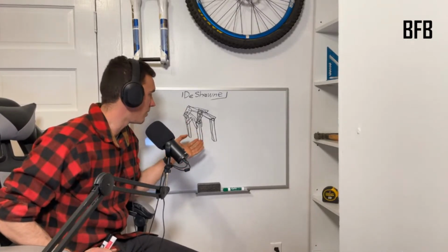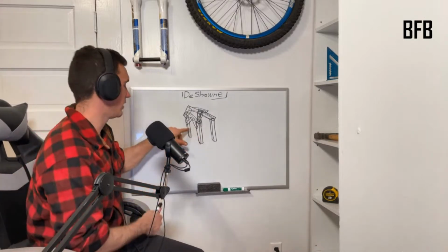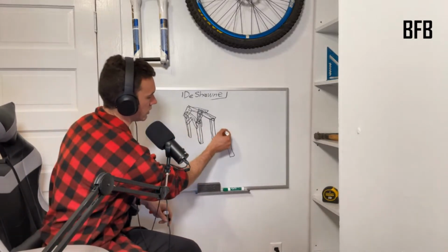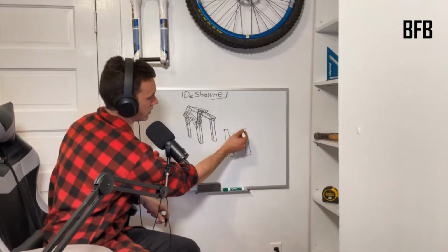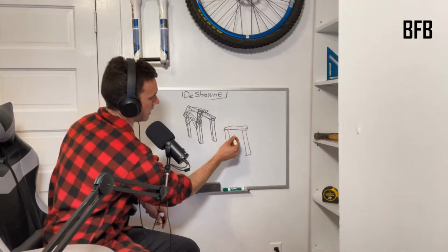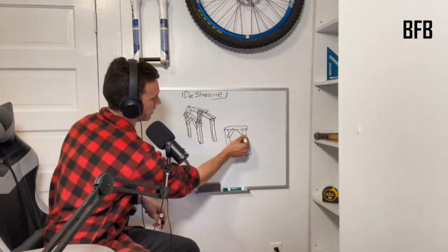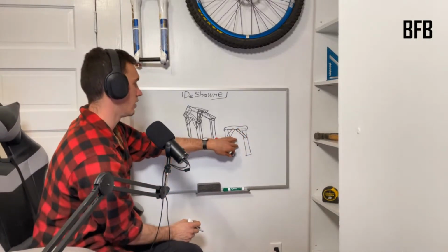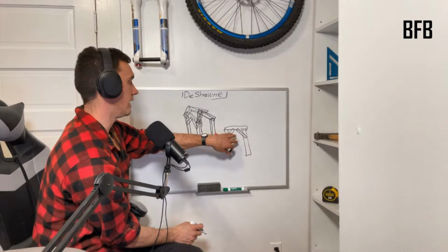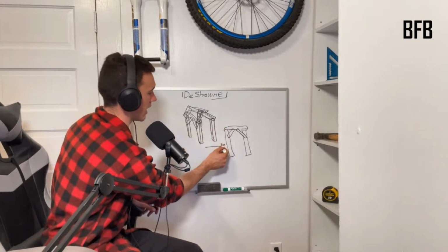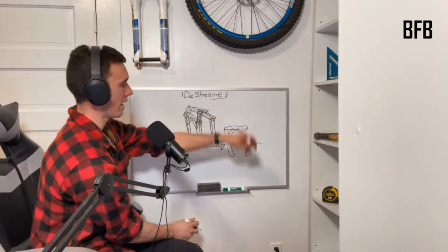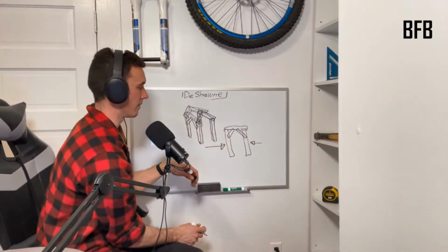Now, the problem with the whole stick framing thing is, let's take a look at this wall over here, for example. That wall is a post, some kind of ceiling thing, and then they put these little kickers in here. Now, wow, that's real straight. So the kickers, what they're doing is they are stabilizing this in the lateral direction. So something tries to rack this wall forward or backward, those are going to prevent it from happening.